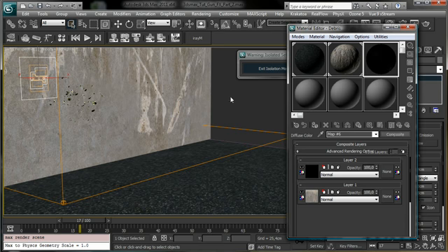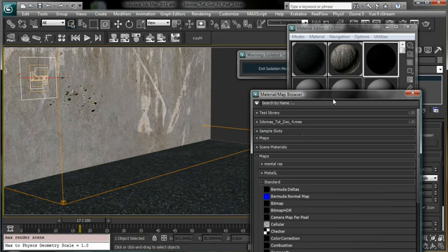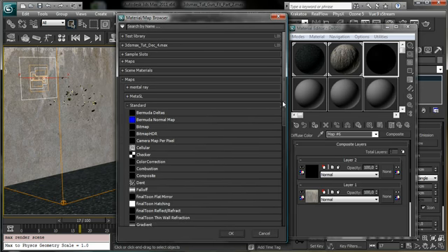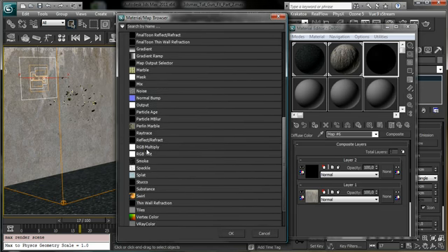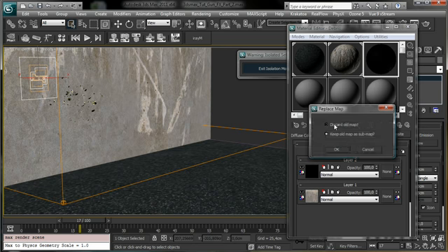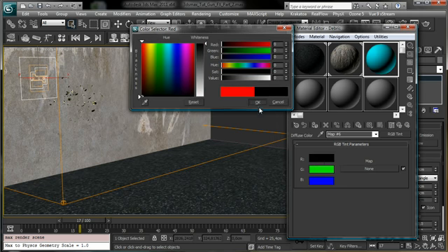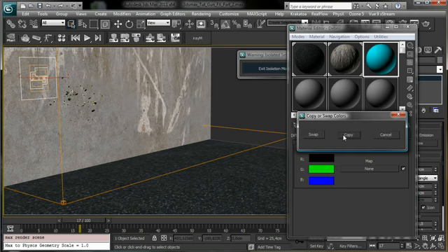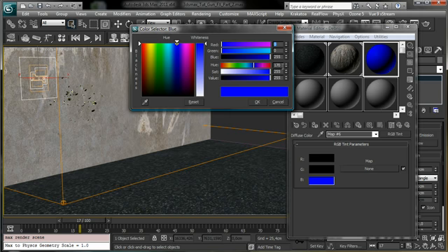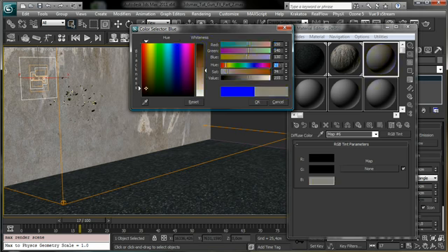We can use a really simple way, an RGB multiplier, sorry, an RGB tint. Okay, discard all map, so we'll use just a color, and we'll use 0 there, so we have black. We copy the black also there, and then on the B color, let's try with 150, 140 and 130. So a color similar to the wall.